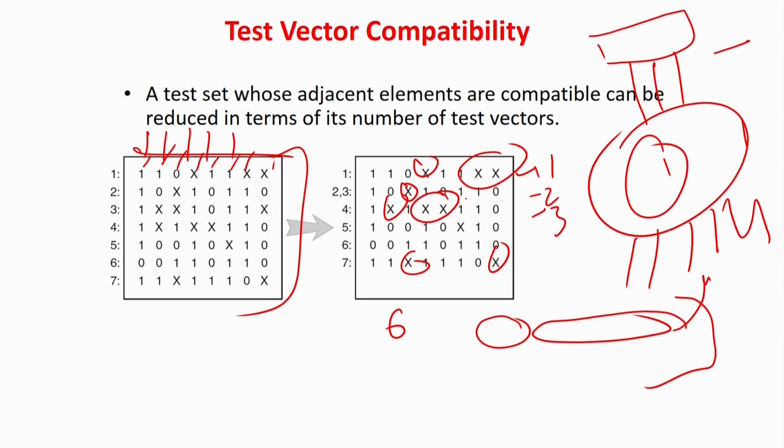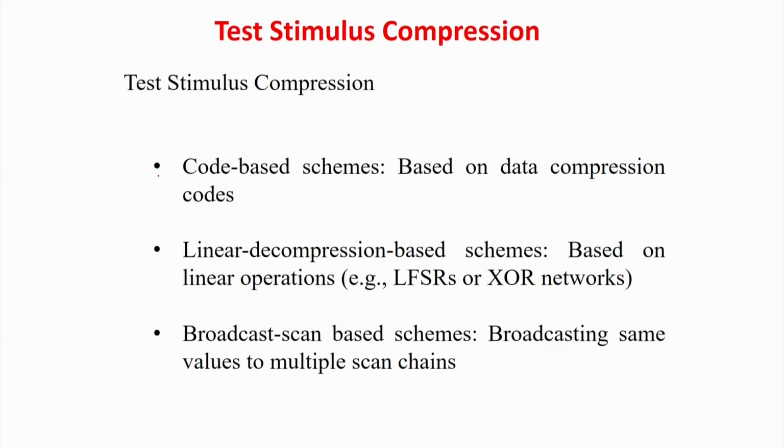That is a more difficult problem to solve, and it will have a huge impact, because by this you are reducing the memory width of the ATE, but you are keeping the same number of channels. If you are booking the same number of channels for the ATE, that pays a higher cost because you are taking more hardware dedicated to your circuit. So if I reduce this width, it will be a better, more optimized solution in terms of cost effectiveness of testing. That is why I call it test pattern compression by reducing the width.